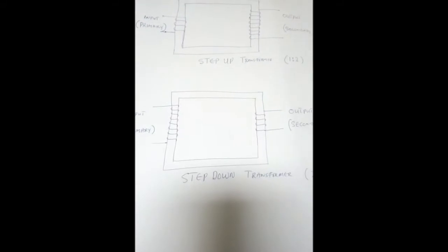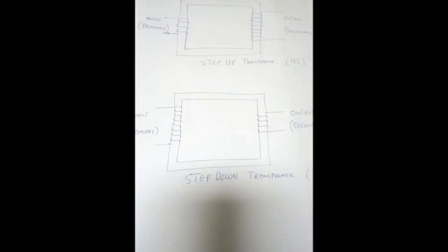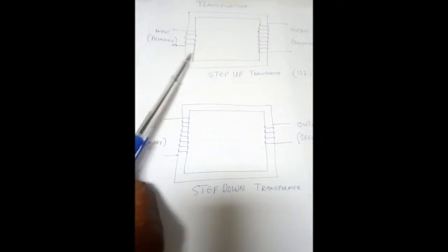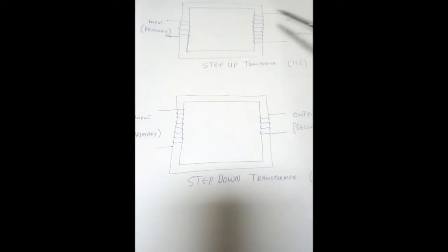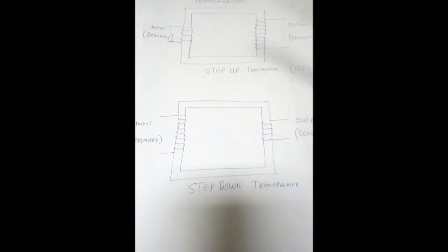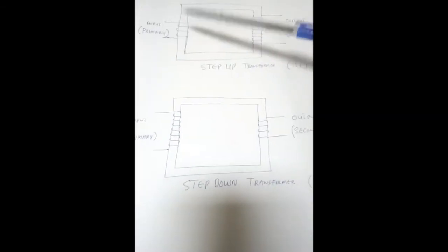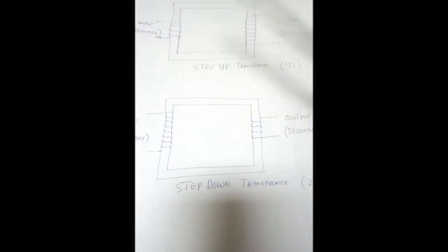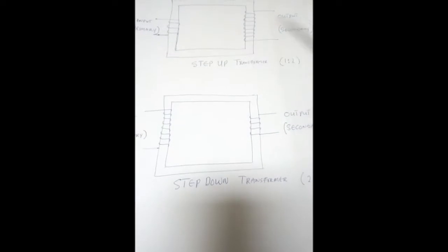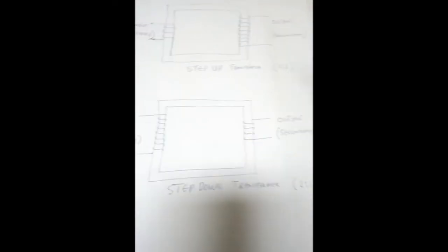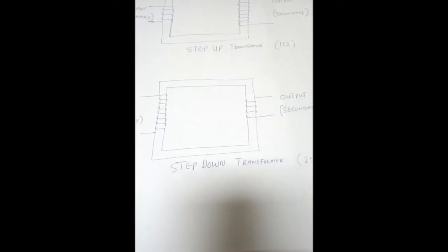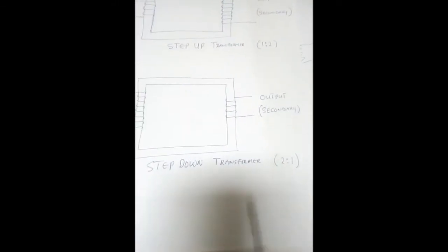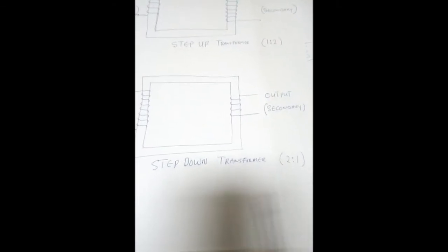So these windings can actually come in different ratios. We have, like, a ratio of 1 to 2. It means the amount of turns you have here will be half the turns you have here. That is for a step up transformer. The windings for the input are always smaller compared to the output windings. For the voltage to be stepped up, it can sometimes be a ratio of 1 to 2, 1 to 10, or 1 to 20, or whatever. And so it applies also to the step down. It could also be a ratio of 2 to 1 or 10 to 1 and all of that.